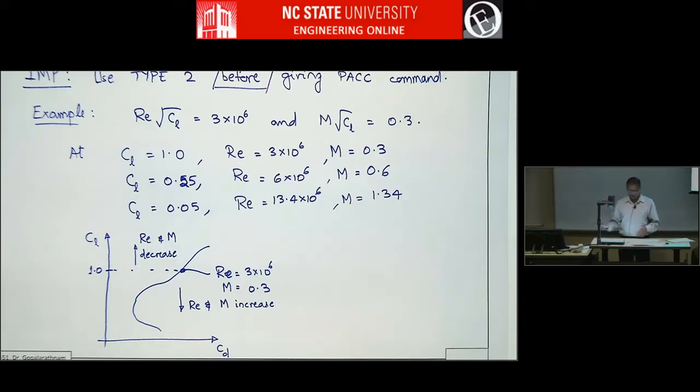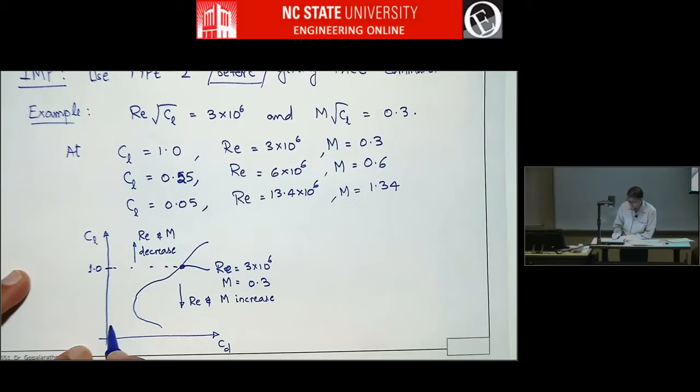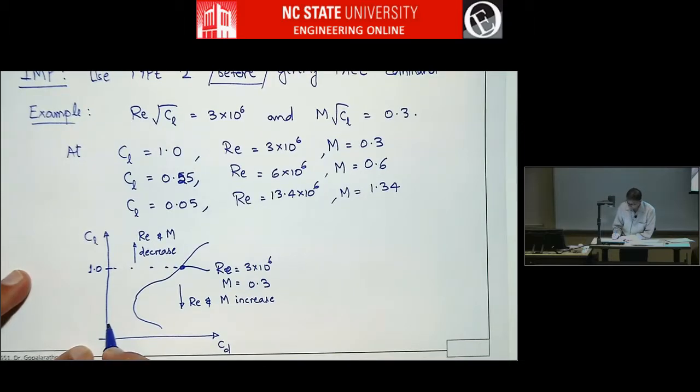The problem though is X-foil is not meant to handle shocks, and so it'll kick out, it'll probably give some error messages. So somewhere here at some low CL, X-foil will start spitting out error or warning messages.